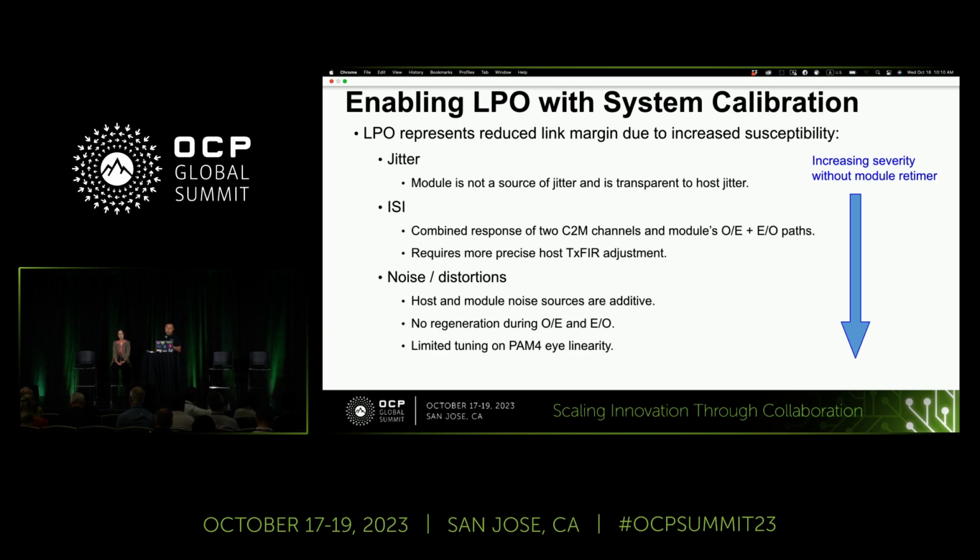And then noise and distortions: the host and module noise sources are additive. And there is no regeneration during the E2O, O2E process. And there is also limited tuning on PAM4 linearity.